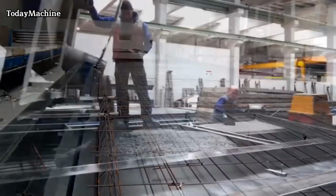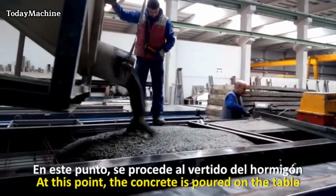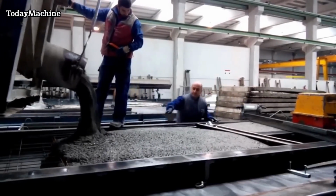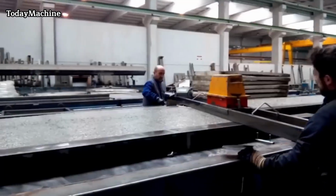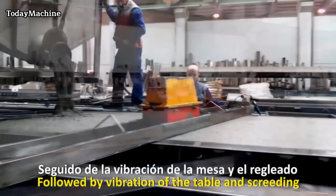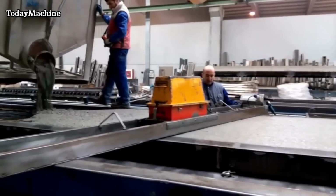To facilitate the handling and transportation of the precast panels, nails are strategically placed within the concrete. These handling nails serve as attachment points for lifting equipment and are carefully positioned to ensure structural integrity. Proper placement of handling nails is vital to prevent damage to the panels during handling and installation at the construction site.